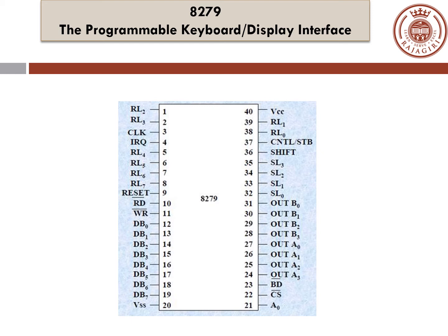So because of that, we have an IC which can offload the work from the microprocessor and do the job of managing the keyboard and the display. So it relieves the processor from these tasks. The disadvantage is, of course, the cost, and the trade-off is between the software approach is the cost versus the processor time and the software development cost.